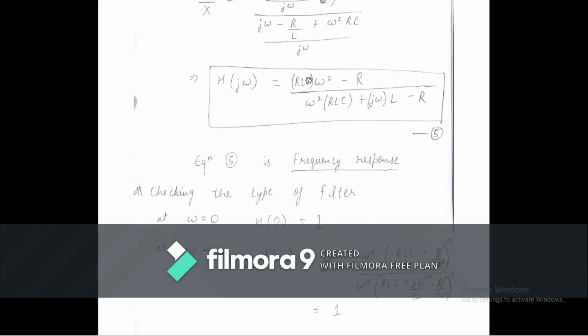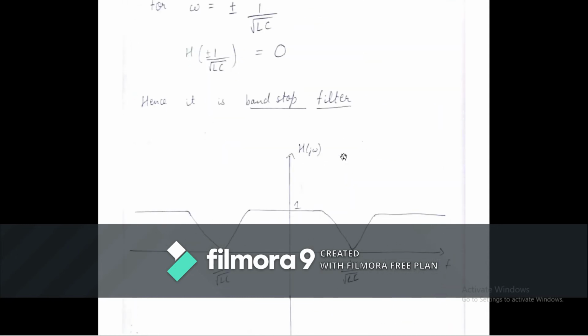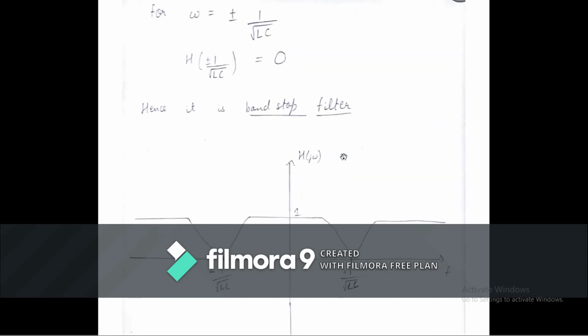If we put the numerator equal to 0, we get omega equal to plus minus 1 by root LC, where H of j omega becomes 0. So by seeing these characteristics, that is at the origin it is equal to 1, at plus minus infinity it is equal to 1, and at plus minus 1 by root LC it is equal to 0, we see that this is actually a band stop filter.